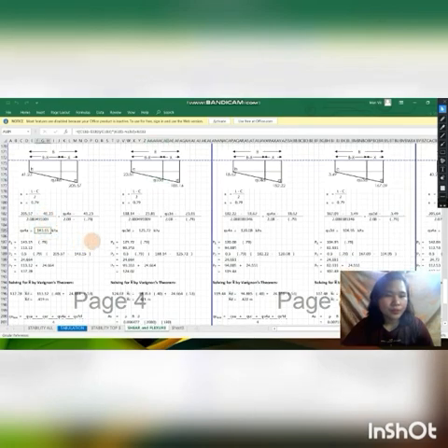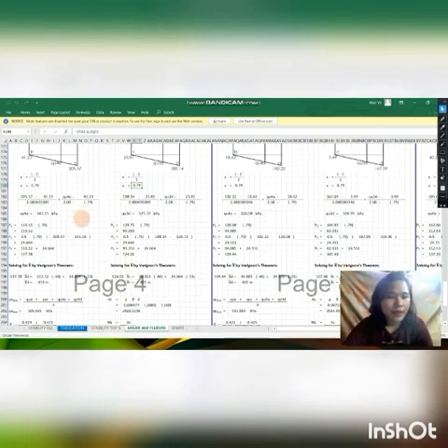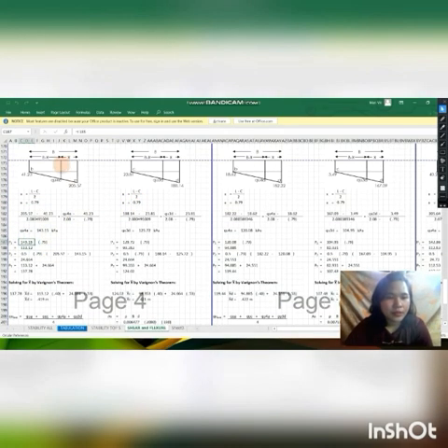So we will arrive at the answer of 143.15 as Q4A and Q4D, sorry, 125.72 kilonewton per meter squared. By using similar triangle, we arrive at those answers. So our X is just the same, 0.79, and for our P1, it is located again here, and our P2 is our triangle part here.